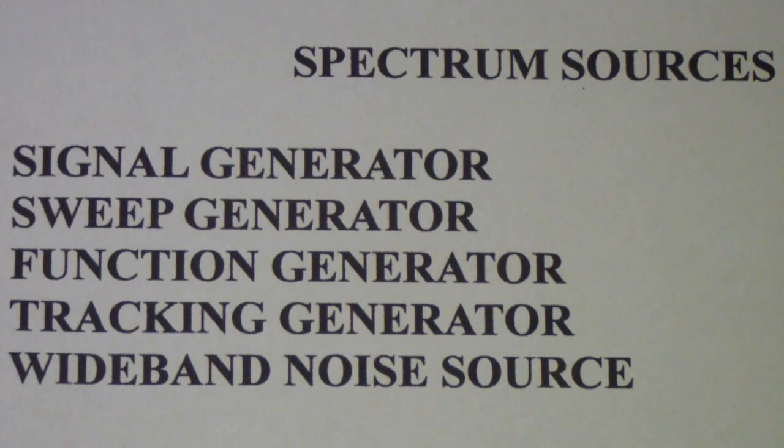Next possibility is a sweep generator, and you may have seen me use this before. In fact, in some of my earlier videos, I used a sweep generator. As long as you use the max hold function on the spectrum analyzer, you can sometimes get a pretty good frequency response or Bode plot for an RF device.